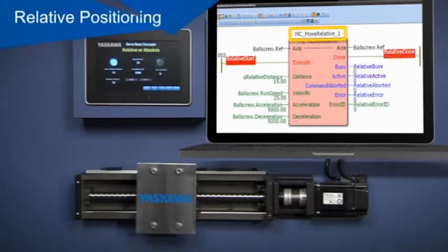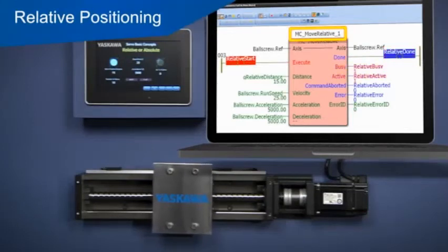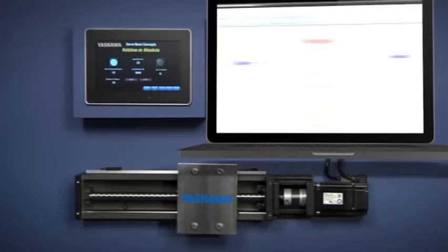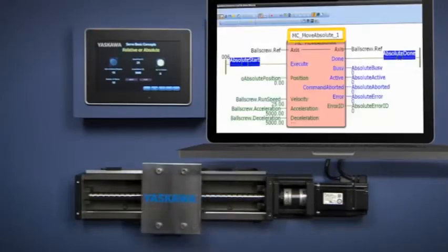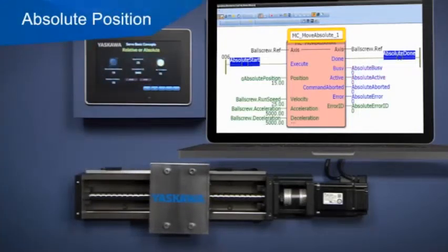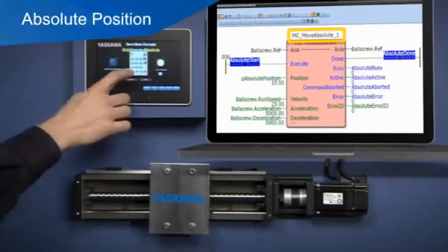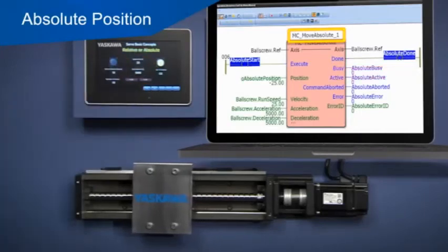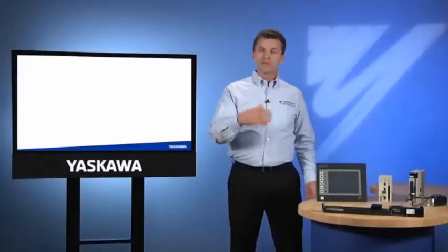This is called a relative move, and this approach is helpful when programming a move that needs to repeat itself several times. On the other hand, the program may have a preset table of positions to which the machine is to move. In this case, an absolute positioning move to a certain position can make programming the controller a lot easier.